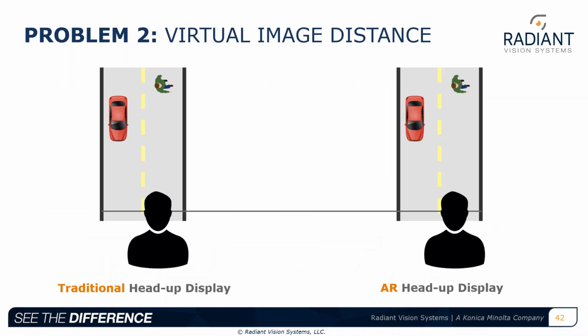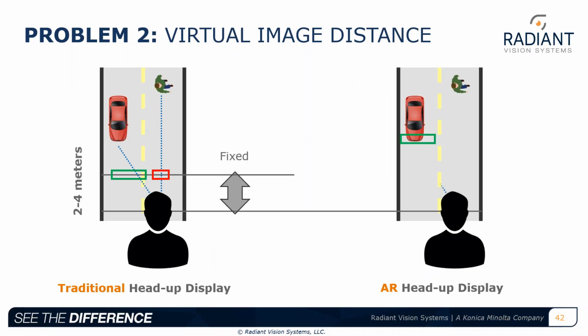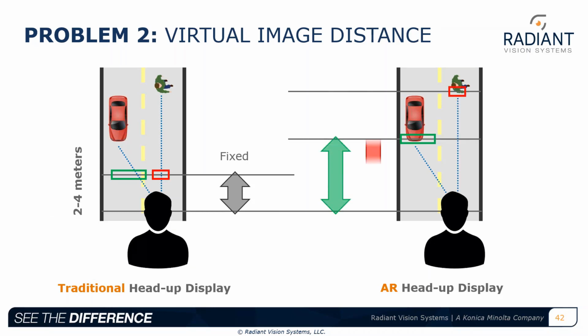So as we've observed, there's a major complexity when it comes to head-up display measurements and the way we deal with different instances and traditional information from a conventional head-up display to an augmented reality head-up display and the information that's being projected. While a traditional head-up display only requires measurements to be taken generally in a single depth and in limited positions, augmented reality HUDs require variable depth and location and flexibility to capture images anywhere along the infinite plane. So again, anywhere from 1 meter out to 20 meters as an example.